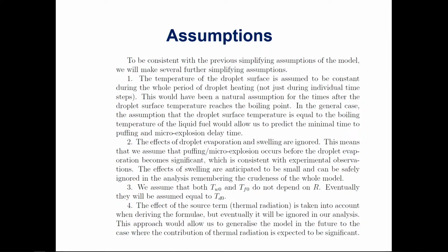And obviously, during the time of microexplosion, swelling and evaporation are relatively small. And then we can assume that initially the distribution of temperature inside the droplet doesn't depend on the distance from the center of the droplet. And then the effect of the source term is taken into account initially, but eventually it was ignored.